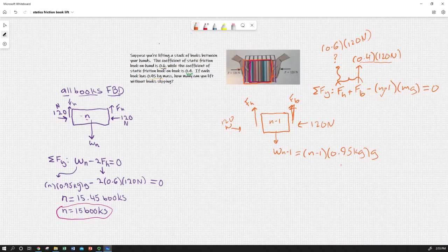Key topics: continue with standard equations of equilibrium, and write or construct sufficient FBDs to capture your limiting case. And as a good rule of thumb, make sure you've captured all the different types of frictional interfaces. Assume something could slip at one interface, maybe it could slip at another if you're not sure. And in this case, the question is asking us for a maximum. How many books?